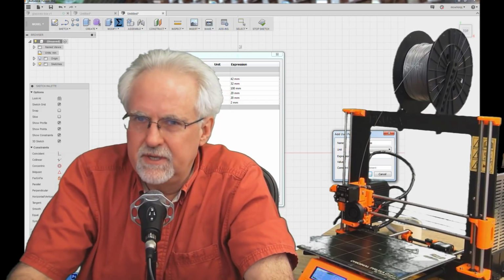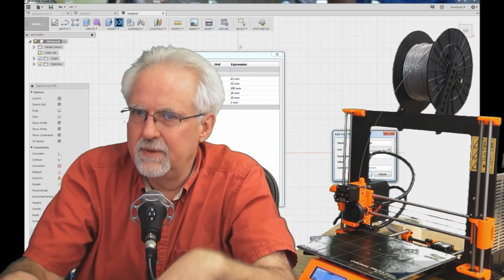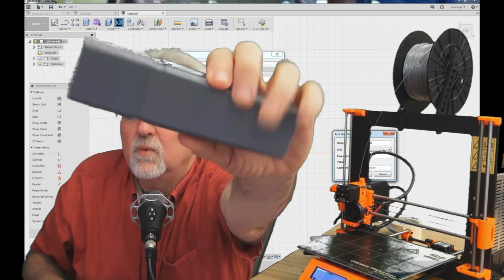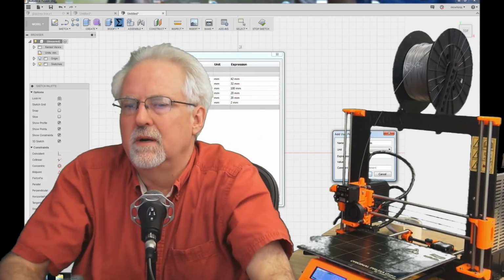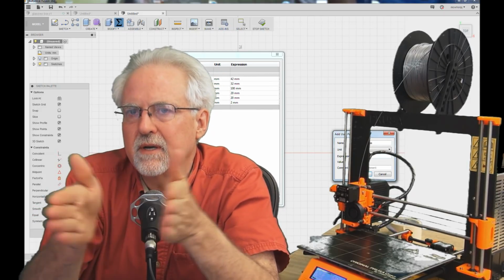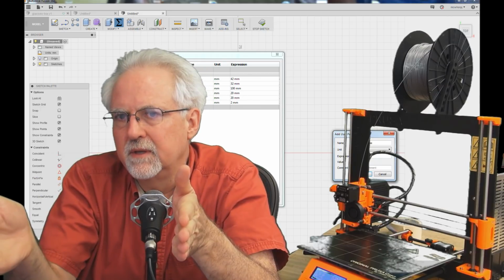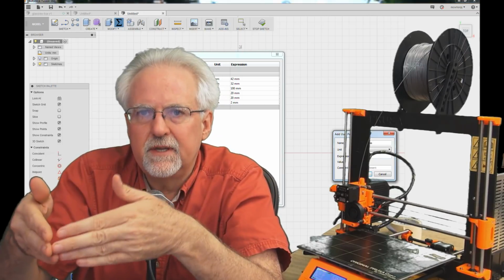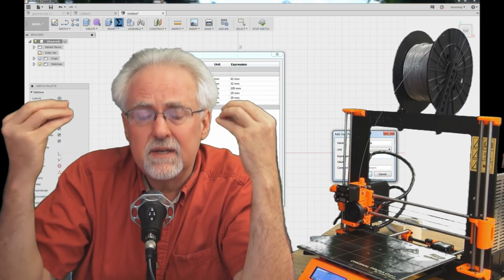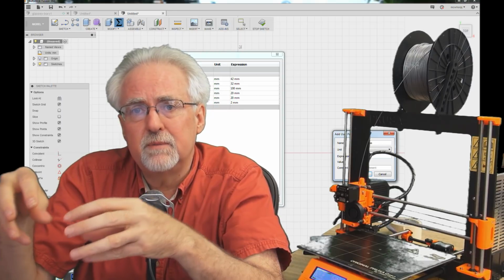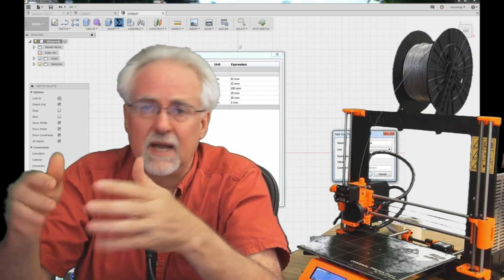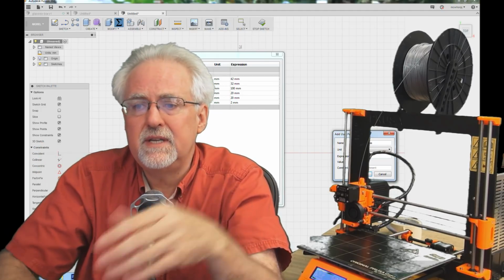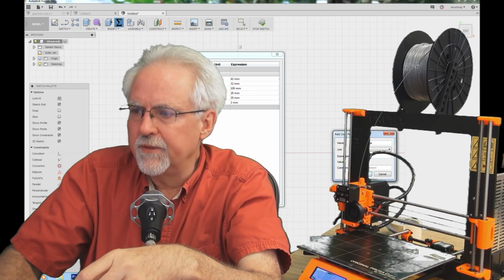And then we're going to say that that is 1. Okay. I want you to stop and think about how this works. Is that smart, what I just did? What if I made the wall thickness 4? Well, then I want the lip thickness to be what? 2. So think, with my design intent, is lip thickness a dependent variable? Does it depend on other variables, or is it independent? Like I could just make it whatever I wanted. I can't make it whatever I wanted. It's dependent. It's dependent on what?